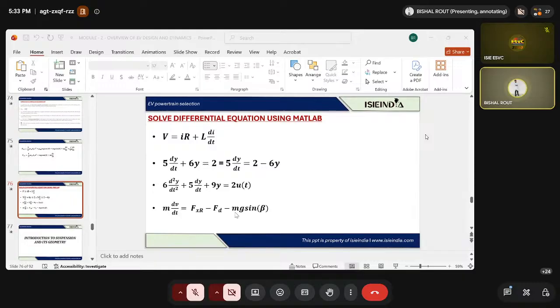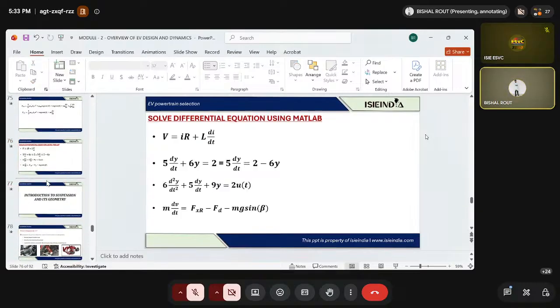And AF has been calculated by multiplying the height with the width, removing the ground clearance. See, if we consider the height of the vehicle, it is measured from the bottom of the tire. But from the bottom of the tire, the height is not all frontal area; they have some ground clearance, right? So you have to subtract that ground clearance, and whatever value remains, you can take as the height. For example, just give me a moment. Let me showcase it over here.